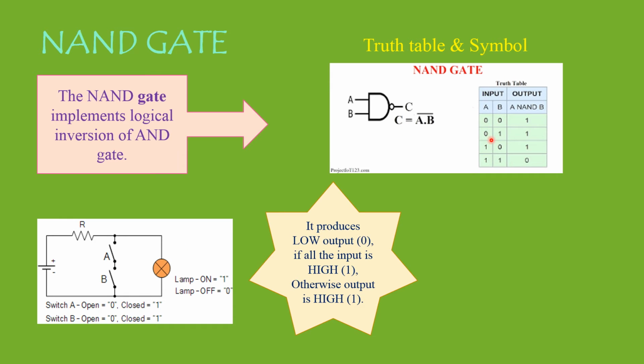So I've satisfied my first condition. And what is the next condition? When either of my inputs is high, my output has to be high. So if either of the switches is closed, then the output should be high. Yes, even for that case it will be satisfied. When either A or B is closed, even at that time, this path will be an open path. So similarly I'll have the same condition arise. All my electrons will be flowing through this path and then I'll have a voltage drop across the lamp, so your lamp will be glowing.